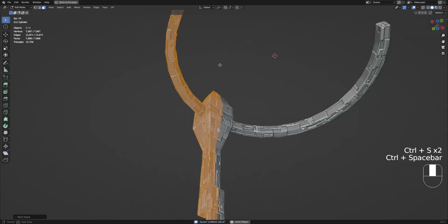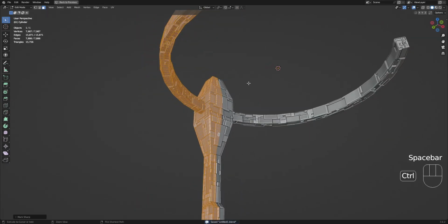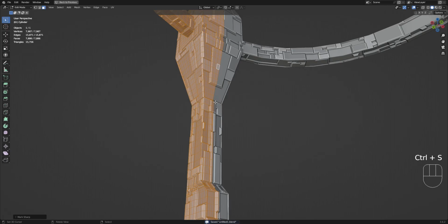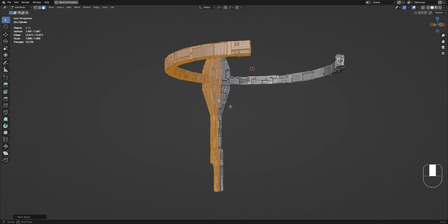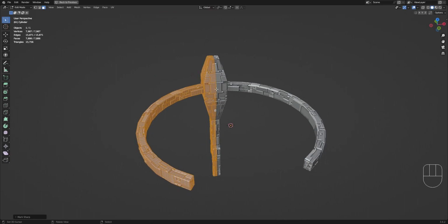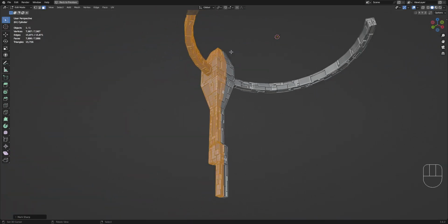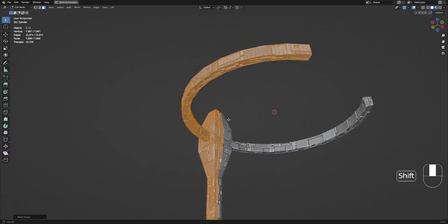What you can do to make it faster to UV this kind of mesh is, before you detail it using plate insets or any random operator, UV it first in the base mesh, and that UV layout will be inherited in the result of the randomization. You still have to repair some of the parts, but at least it's easier for you.